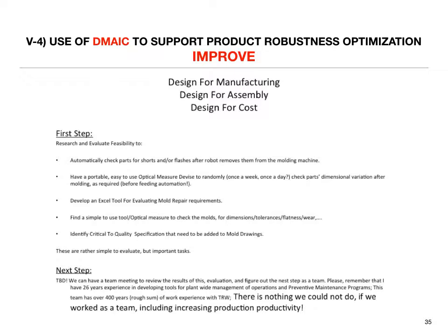Then develop an Excel tool for evaluating mold repair requirements. What is happening with the mold repair document, what they're repairing, how often they're repairing, how they're repairing, and find a simple tool to use for measuring, checking the molds, dimensions, tolerances, flatness, wear, and identify critical to quality specifications that need to be added to drawings, mold drawings. They were simple but very important.